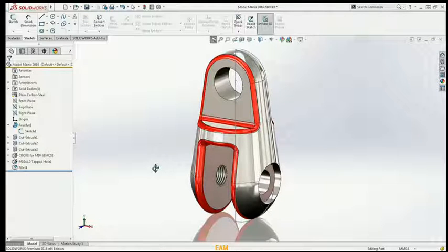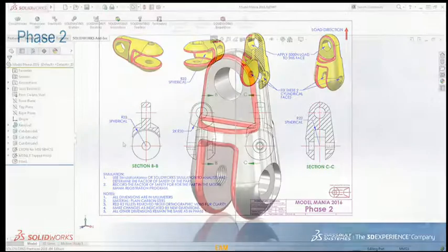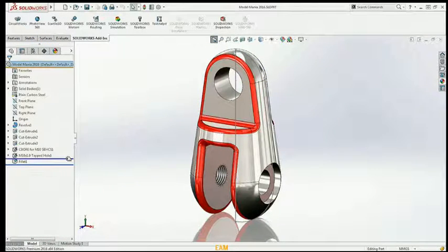So that's phase 1. As you're done with that, we give you another drawing to make a change. As I mentioned before, those ledges at the top go from planar to cylindrical, and the ceiling at the bottom, if you will, inside of that pocket becomes spherical. When I look at this, the first thing I think of is replace face. Maybe you don't think of that, but maybe after I go through this little exercise, you'll say, next time, that's what I'll think of too.